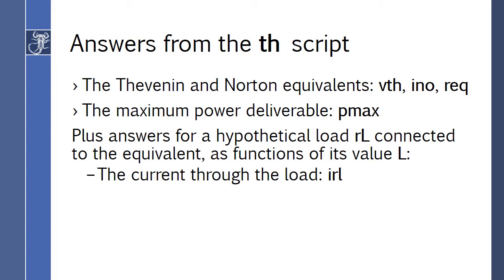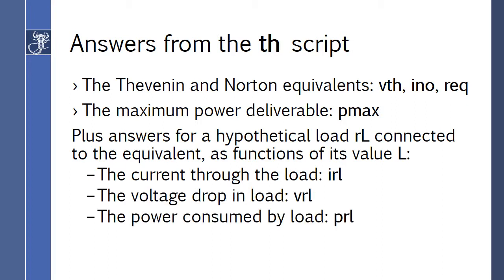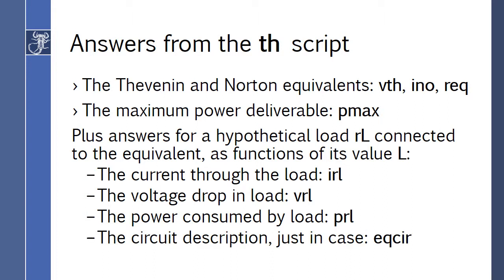We get, for example, the current through the load, it is stored in IRL. We get the voltage drop in the load in VRL, and we get the power consumed by the load in PRL. Besides that, you get the circuit description of this equivalent with the load, just in case you want to play with it. It's a string and it's called EQC, or equivalent circuit.